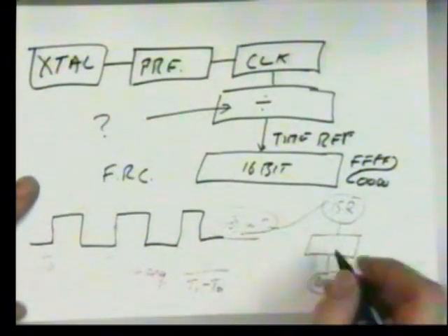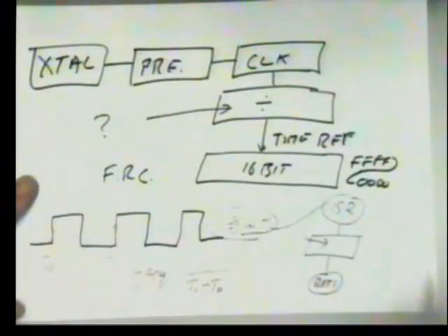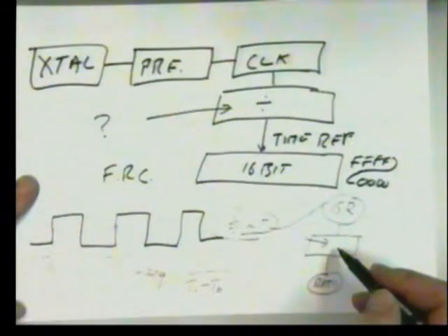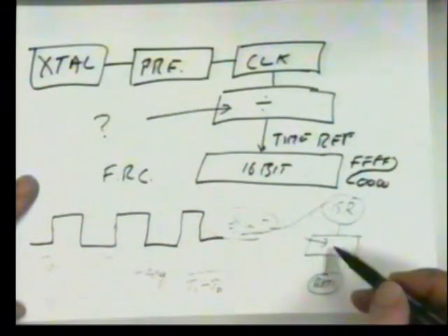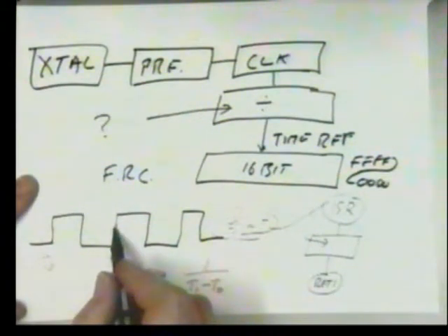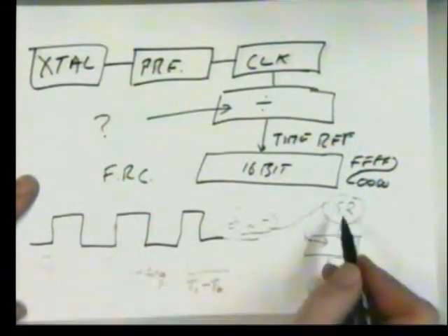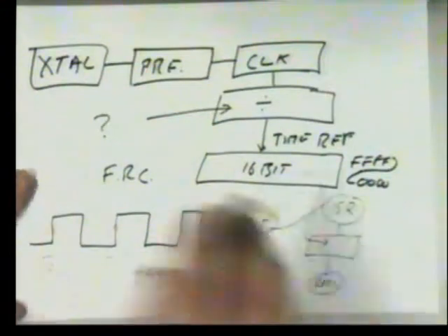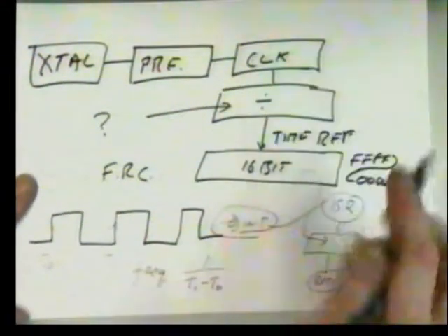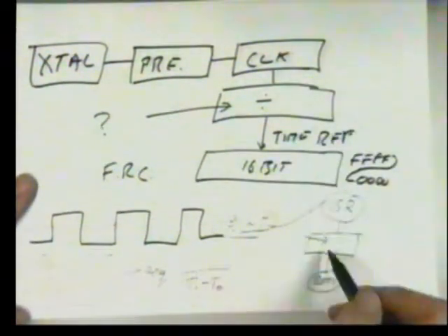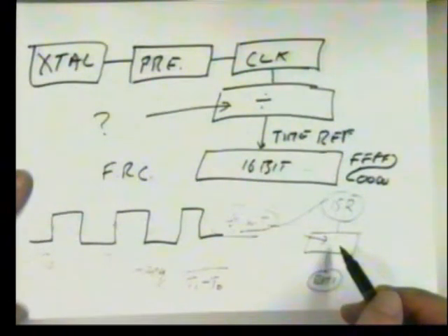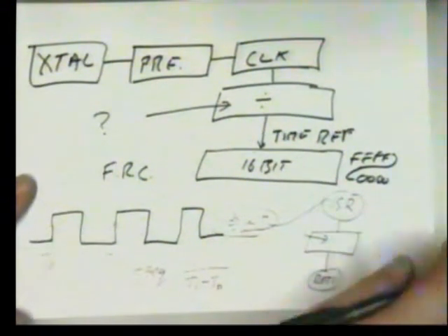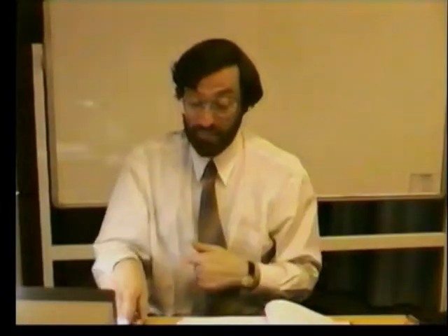And what our program does here is it takes a copy of the current timer, and that number now we know was near instantaneous. The rising edge there issues an interrupt to the interrupt service routine. Everything else is stopped. And we immediately read the timer and we store it for later processing. That is an interrupt approach to the system.